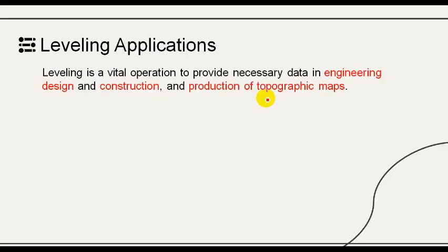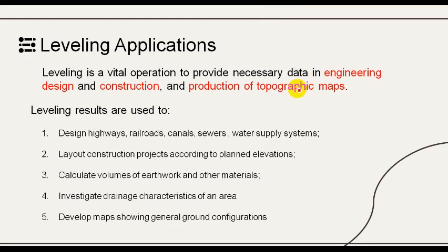Leveling has many applications. Leveling is also considered as the vital and important aspect of surveying since it provides necessary data in engineering, design, construction, and production of topographic maps. So results in leveling can be used in the design of highways, railroads, canals, sewers, and water supply systems.